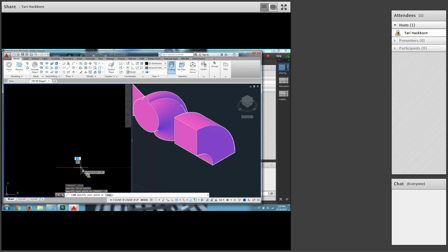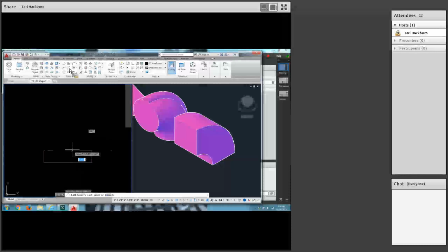And then we can come up 3/16 of an inch. I drew it in the wrong direction. Okay, and come up 3/16 of an inch right here. And I can do the same thing on the other side. I can make this a little bigger for you now. 3/16 of an inch up here. I know that I can come over 1/8 of an inch because I see that dimension. And then this line right here comes to a point that's going to be 1/4 inch from the line on the left, so that means you're going to move this line a 1/2 inch.